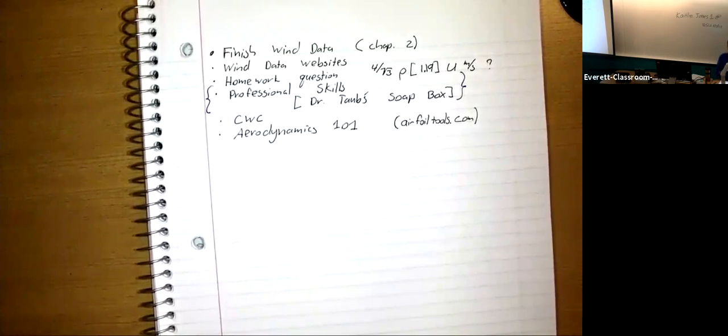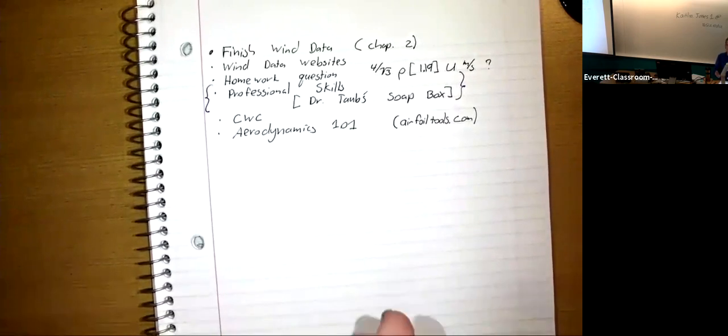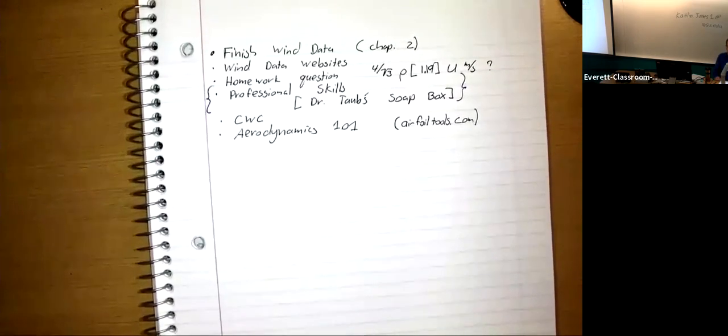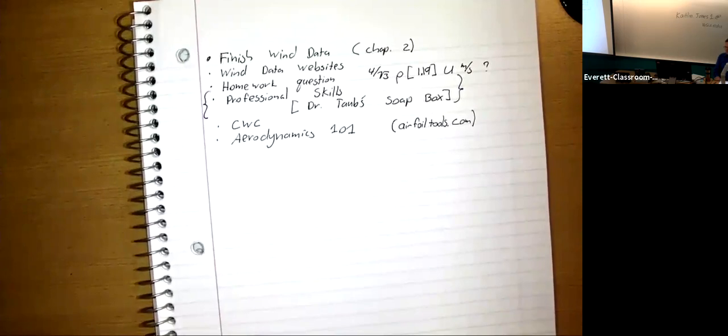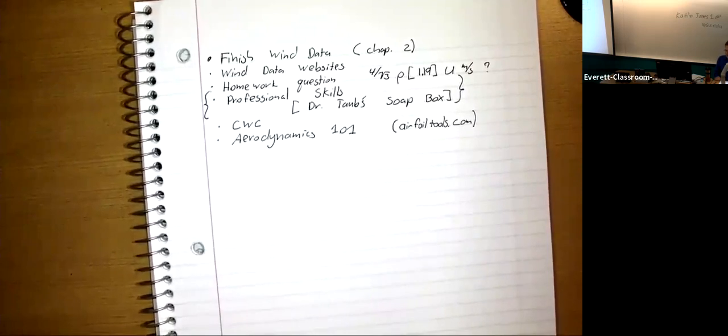Multiply the number of hours that the wind was blowing at 1 meter per second by the power that's produced if the wind was blowing at 1 meter per second. Multiply the number of hours that your histogram says the wind was blowing at 3 miles per hour by the amount of power that would be generated if the wind was blowing at that speed. That'll tell you the amount of energy that was produced over the course of the month at the time the wind was blowing between 2 and 4 miles per hour. Just keep doing that for all the bins and then add them all up.